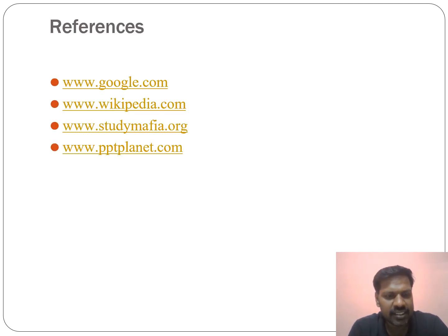So these are the references. To summarize, three-phase induction motors are widely used in industry because they are simple, rugged, low cost, and require little maintenance. They work by creating a rotating magnetic field in the stator, inducing current in the rotor, and producing torque due to the interaction of the stator and rotor fields. The rotor speed is always slightly less than synchronous speed, and this difference is quantified by the slip.